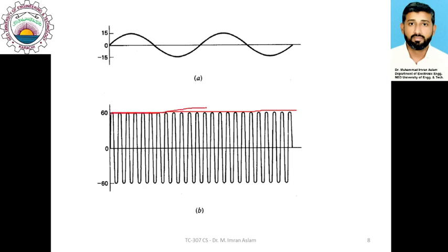This horizontal line is representing the amplitude of this carrier wave. This amplitude actually serves as the baseline for this modulated signal. So if we superimpose this message signal onto this carrier wave, it would look somewhat like this, and you would see that the overall message signal or modulated signal would follow this type of pattern.